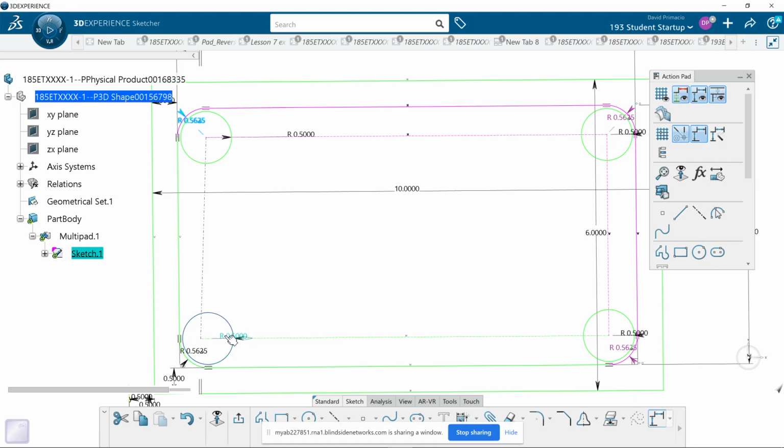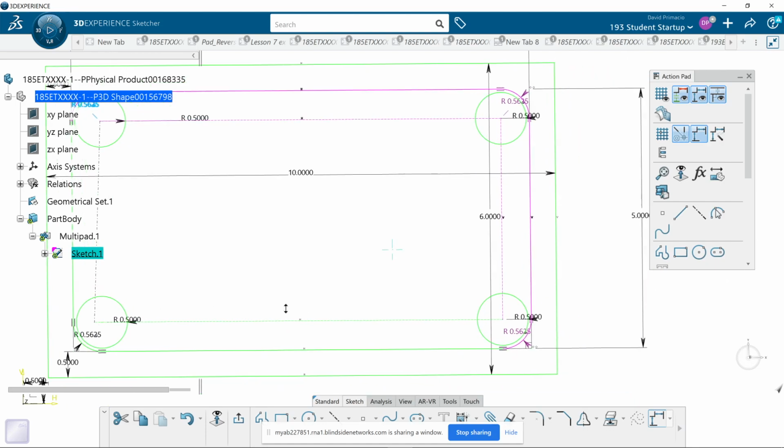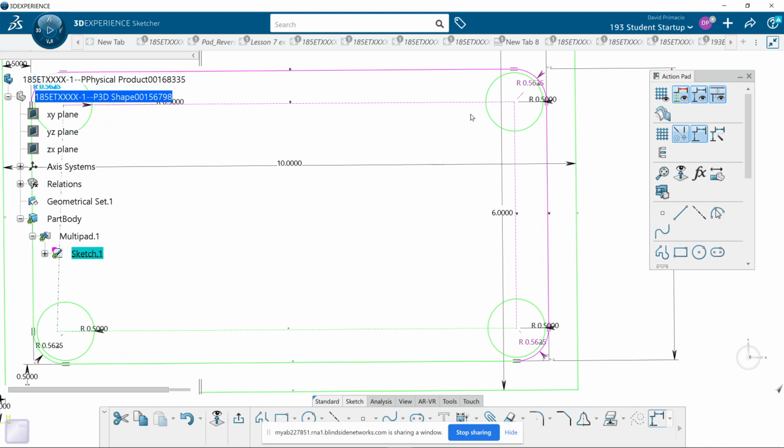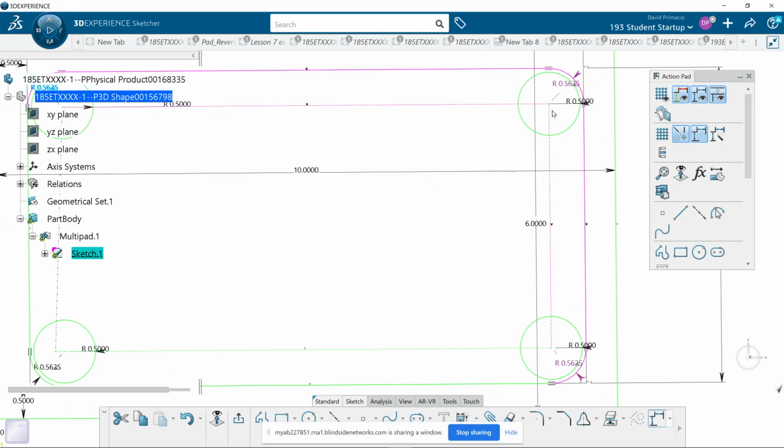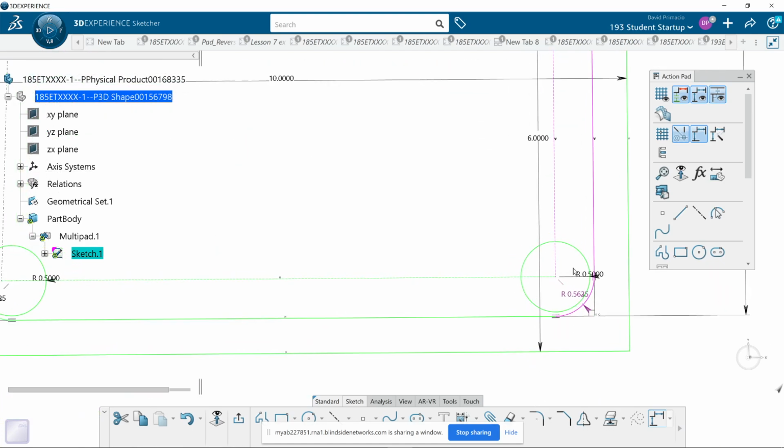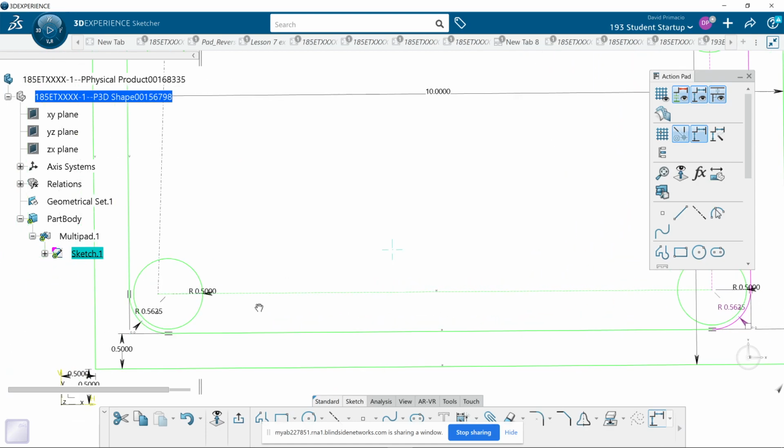Why didn't one of these, this line here, oh. Might not have hit the center point. Yeah, I must have missed. Anyways, this wouldn't be a 90-degree angle anymore, because this will be a radius as it makes its turn of 0.0625 radius in here, which means I could get right up in there and machine that with a 1/2 inch radius.